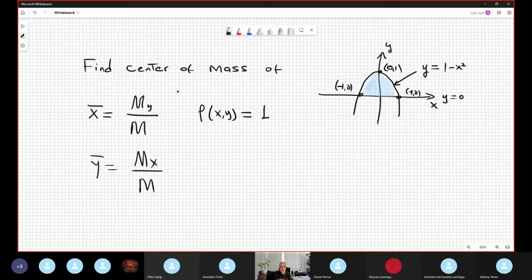Because the difference between center of mass or center of gravity and centroid is that you suppose the density may be variable. If it is a function in 2 dimensions, and suppose the top part has more density than the bottom part, then the center of mass is shifted, no? But in this case, the density is uniform, it is constant. So now actually it's a centroid, no? A centroid is like a center geometrically, no? Okay, cool, no problem. Okay, so let's do the double integral.